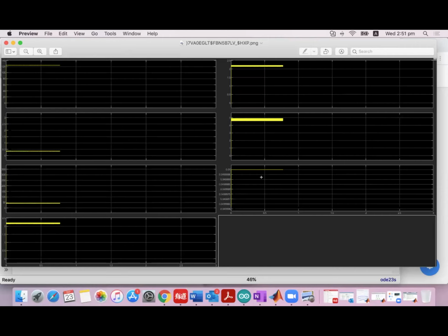I guess this graph is your duty cycle. If your duty cycle is this small, then that's not right. And I can see that you trace the maximum power starting from when duty is 0. I suggest that you track your duty from up to, I will not say 1, because 1 is when input is equal to output, and that cannot be reached. So I'll say 0.9 or 0.95.